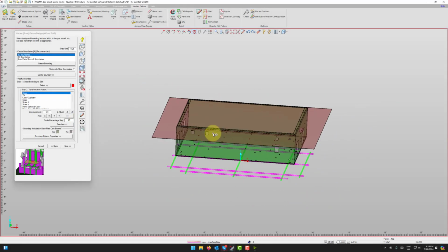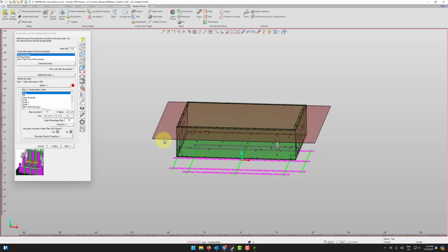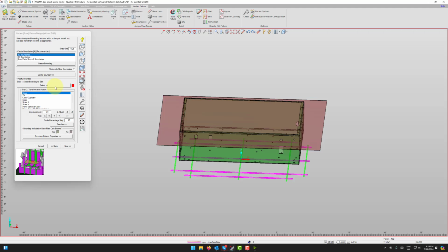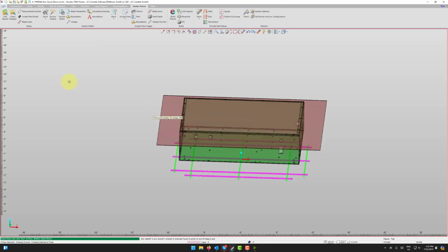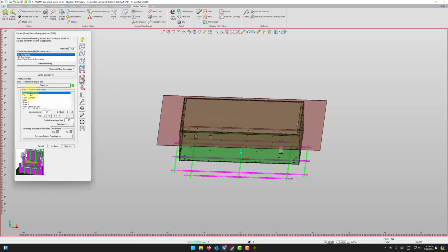And now we're looking at a fixture, and we want to change where the height of these boundaries are at. Obviously, the simplest way to do this is select the boundary, and then select the transformation tool. So you want to do move, right? And then set the increment you want to move at, and then choose the axis, right? And that's a very simple, straightforward way of doing that. If you want a bit more control though, you can actually click the freeform button. The freeform button, right, is going to ask us to work with a copy of the selected boundary or not.